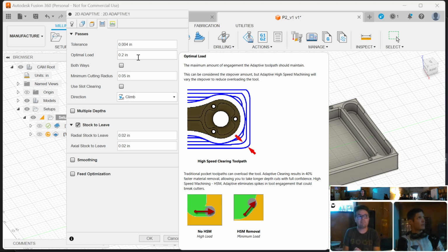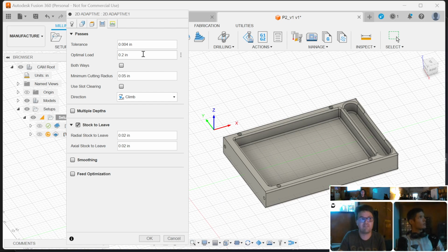It is generally better to do a deeper cut where you're using more axial length of cut and less radial length of cut. You'll get more removal that way. But we're using a 1/2 inch bit, so 0.5, we're at 0.2 out of 0.5, yeah, that's slightly less than the radius of the tool. That's a good point. Climb milling is the right default.